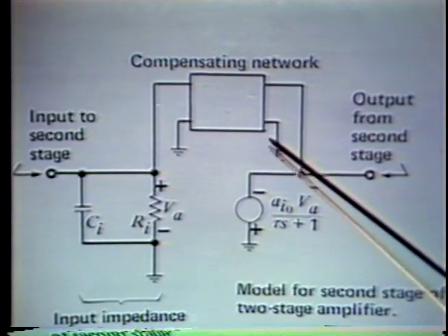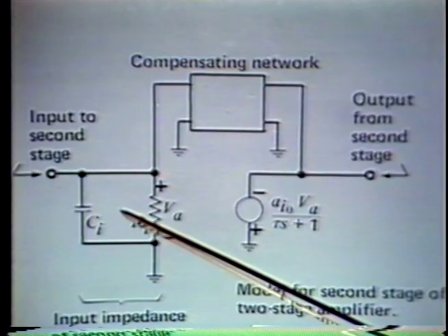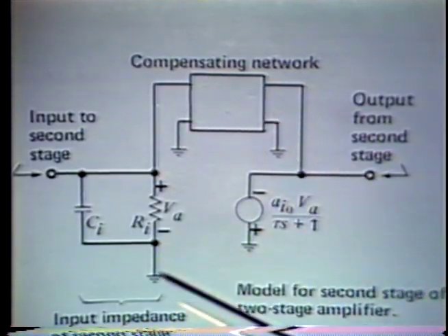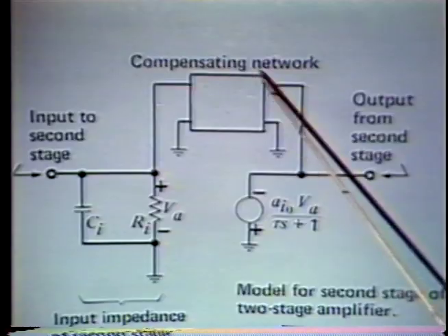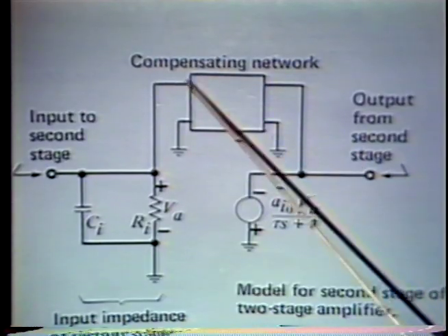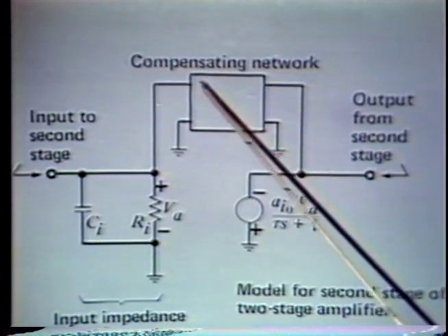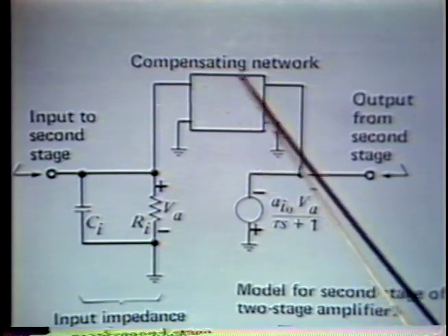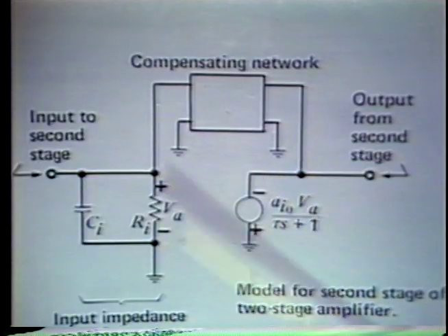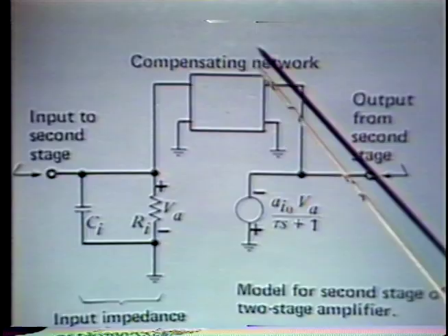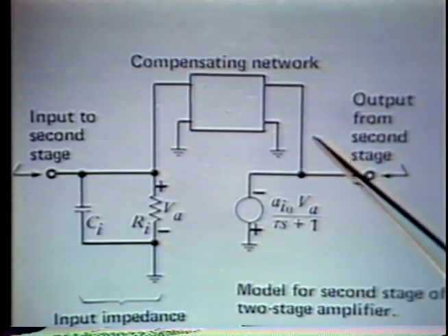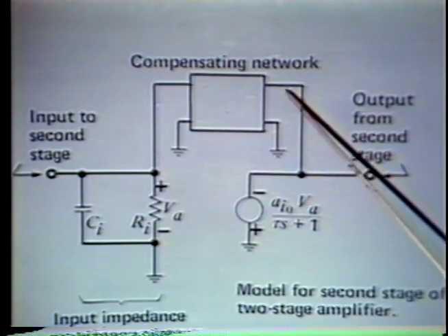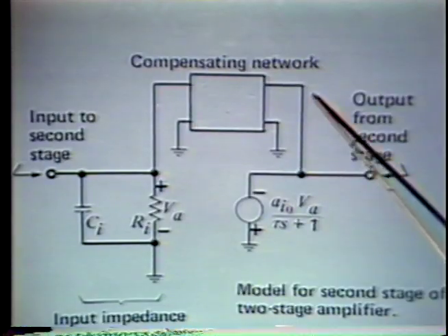Well, if at crossover in the minor loop, this network looks principally capacitive from here to here, in other words, if it looks like a single capacitor or if it looks like a T that has two capacitors across the top and a single resistor down on the vertical portion of the T, then at high frequencies we get simply an attenuation between this voltage and this one.